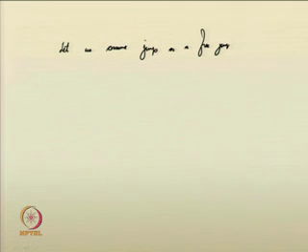So, we need to take those into account when we do the analysis for sloping channels. Let us assume the jump as a free jump. In our earlier lecture we suggested that tailwater conditions can affect the jump location, and so we are assuming that the tailwater depth is free, that is whatever jump depth is occurring, that will be the downstream depth.